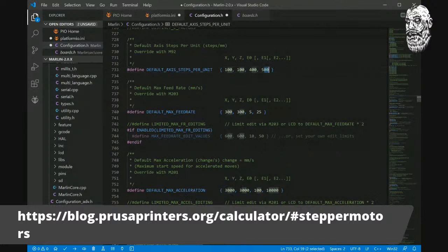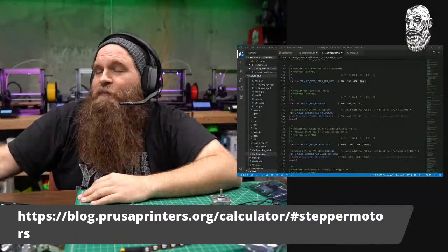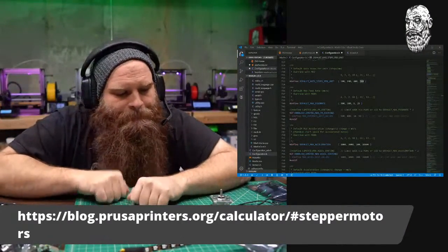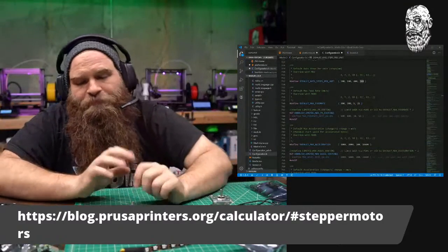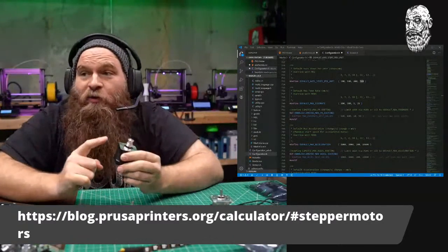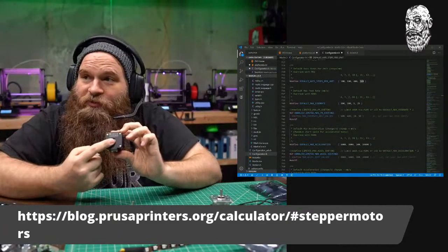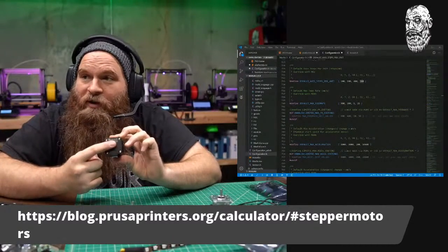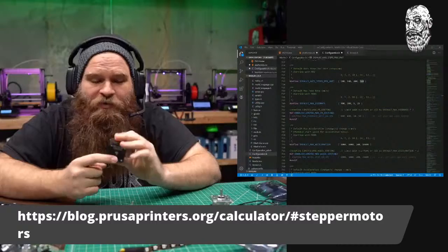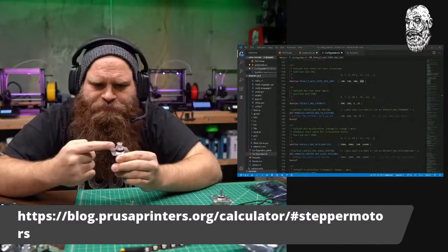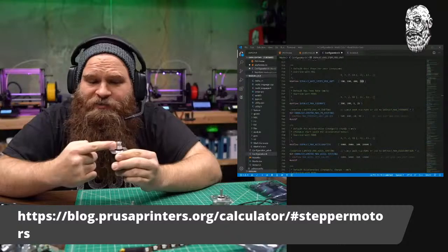And then our extruder. Now this is where it gets tricky. Let's go back to me on camera. Right here. How do we figure out our extruder E-steps? That's a fun one. It all has to go back to the motor degree, what degree motor it is, how many micro steps it is. So this is a 200 step motor. Not micro steps, how many physical steps it is. And then also what size thing is on there.